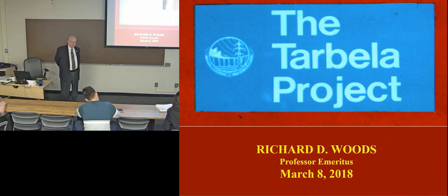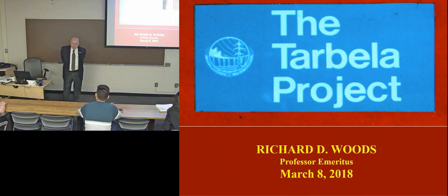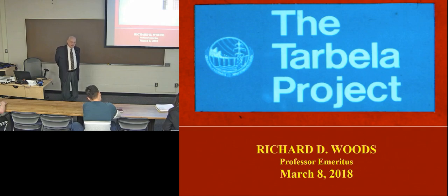So we're going to see that there are issues associated with, first of all, hydrology. Is there going to be enough water to fill a reservoir? Hydraulics, how does the water move? Much geotechnical work. However, this is not a clay core dam. This is a rock fill dam.